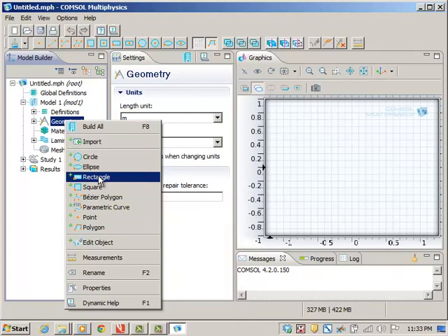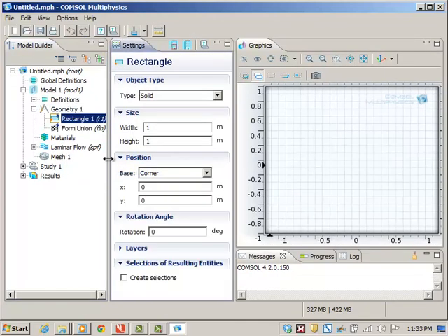Say I want to build a rectangle, so I just select this rectangle, and then you can define this length and the position. So let me say width of 10 and height of 1, and let's move this corner to minus 0.5, just to make the 0 as center line, y is equal to 0, x-axis.